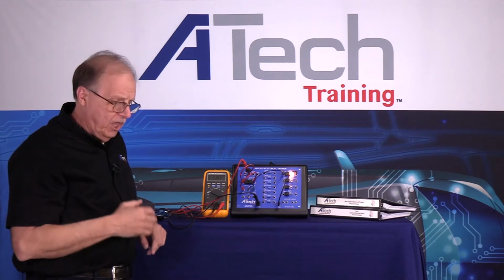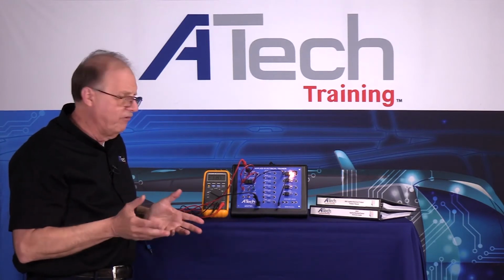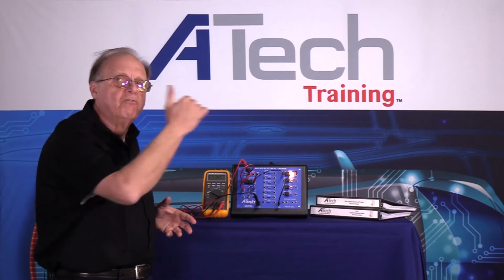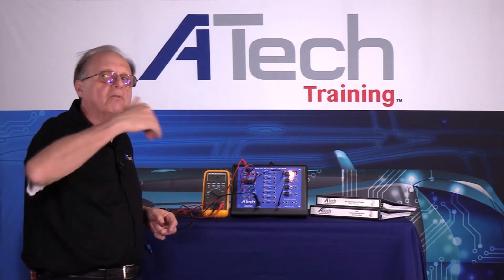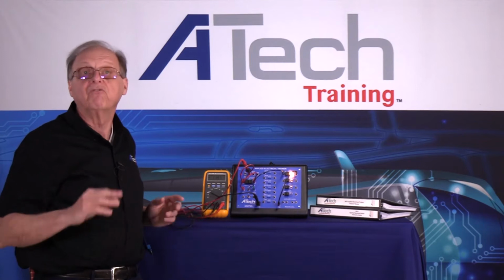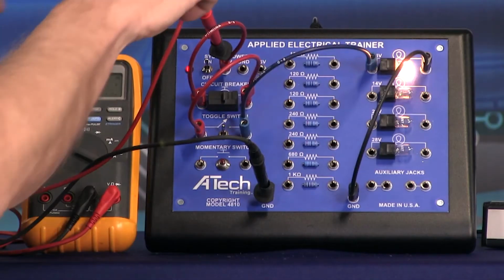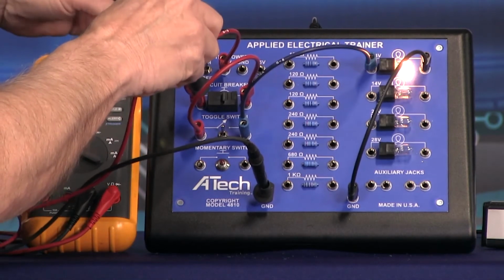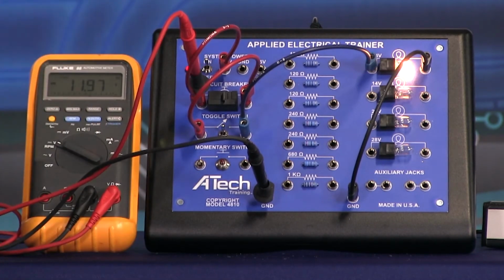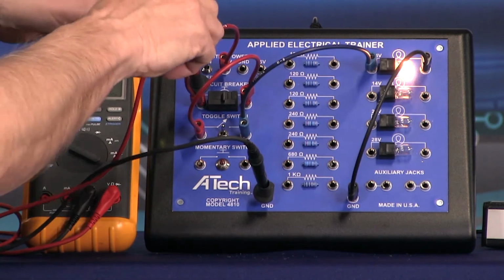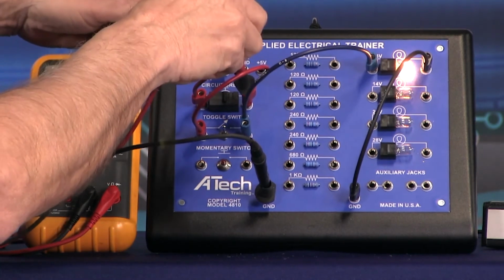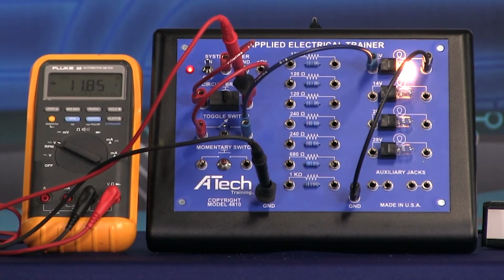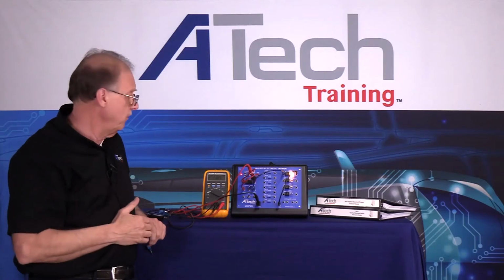Now, if I was checking a circuit, there are different ways of checking it. Some people start from the fuse and work their way down. Other people start from the ground and work their way up. It doesn't make a difference how you do it, just as long as you do it. So I'm just going to go up here. I have 11.97 into my circuit device, or my fuse. That's why we should always check a fuse on a circuit to make sure it's correct. And then I'll go on the other side of the fuse. I got 11.85. So I know for a fact that on that circuit breaker I have dropped some voltage, which you will do as you go across. It's being used up as it goes across.